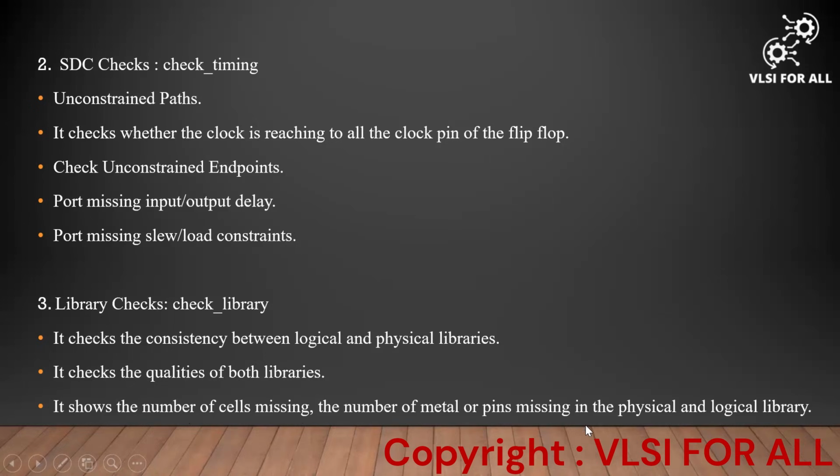the number of metals or pins missing in the physical and logical library. If in the physical or logical library any cell information, pin information or related metal information is missing, that comes under the library checks with the help of this command. We have to report it to the front end team and have it corrected.